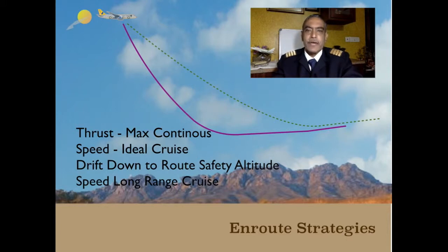Of course, if the route contains very high obstacles which are not meeting the legal requirements of obstacle clearance altitudes, then the pilot, after securing the engine, will maintain the best lift by drag or best climb speed to drift down as low as possible till he clears the point of high obstruction, and then quickly change over to another profile.